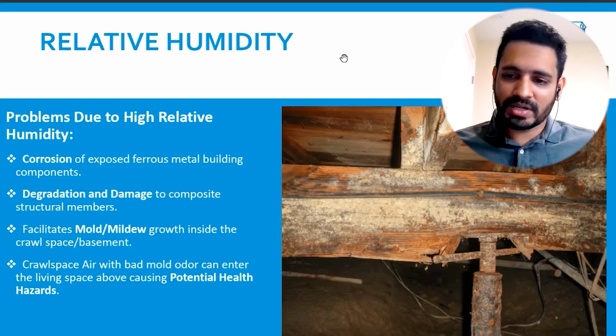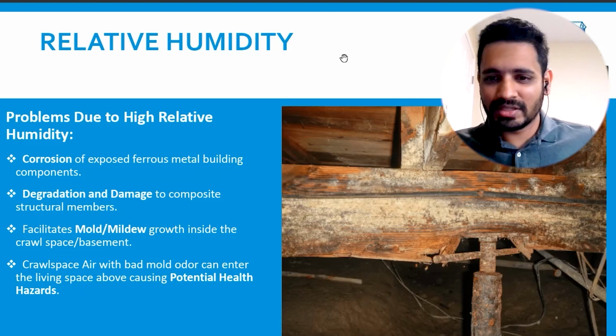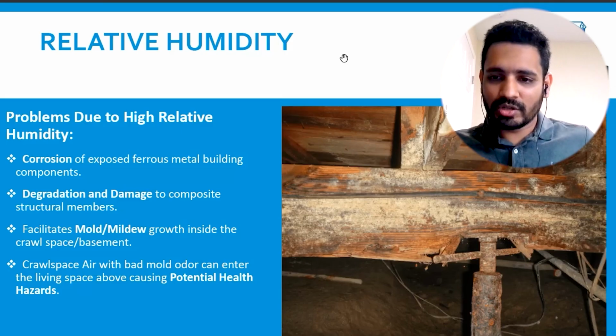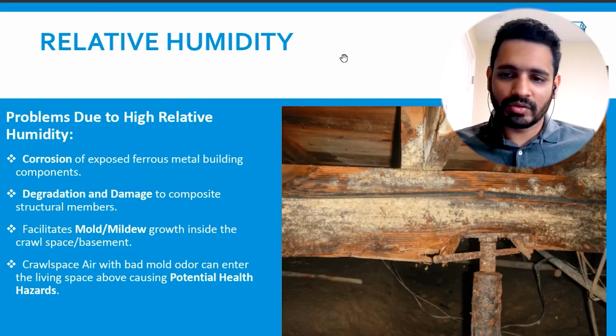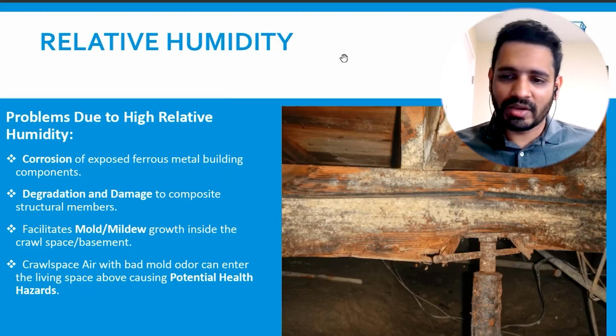This was an inspection back in 2020, I believe. I did this inspection. We did quite a bit of work here to control the moisture, did a lot of fixes for the wood framing, replacement of the wood framing in most cases. The screw jacks were replaced with pressure treated wood posts to get more life out of them.